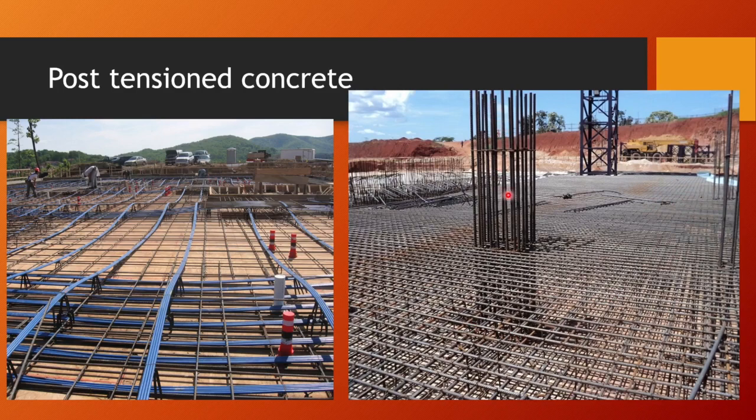With these slabs and reinforcement bars, once this is all poured, there'll be shuttering or a post-form system put around these columns, like a mould, and then concrete is poured in. Concrete will probably be poured up to around about here, and then you'll just see these bars sticking out at the top.